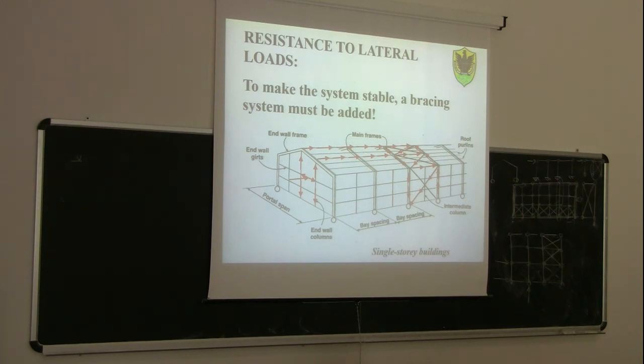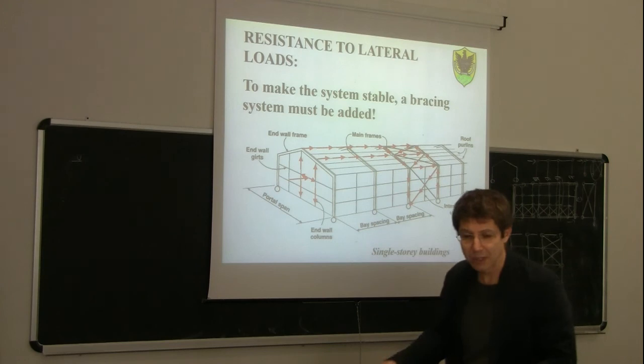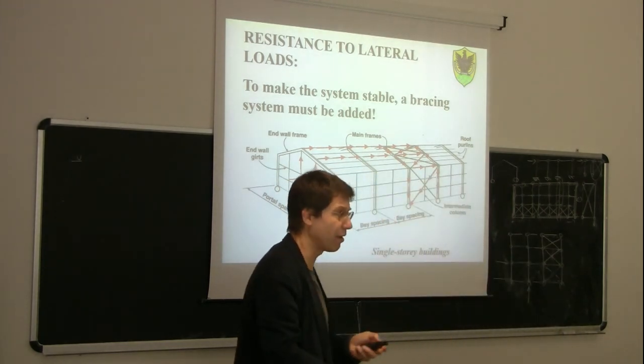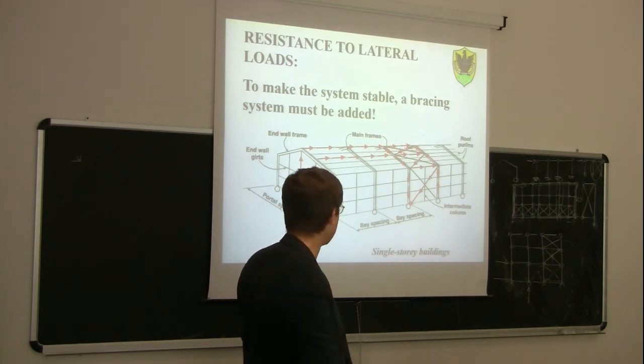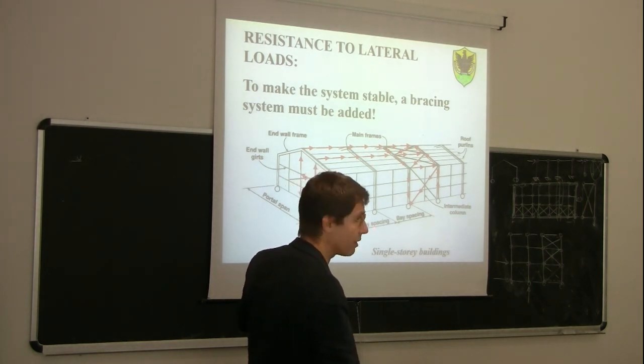Okay? This will be important because later on, when it comes to design the members, we have to remember that when we are going to design those frames which are part of the bracing system, they will be stressed not only by the in-plane load, but also by the out-of-plane load, because they are part of the bracing system. Okay? While instead, in simple frames, for example, this frame here, this one will be designed only under the in-plane loads, not the out-of-plane loads.